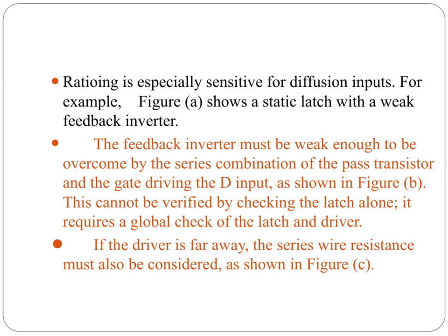It's important to note that this setup can't be properly verified just by examining the latch on its own. We need to perform a global analysis that takes into account both the latch and the driver together. Additionally, if the driver is located at a significant distance, we need to factor in the resistance of the series wire as well, as demonstrated in Figure C. This ensures the signal integrity is maintained throughout the circuit.